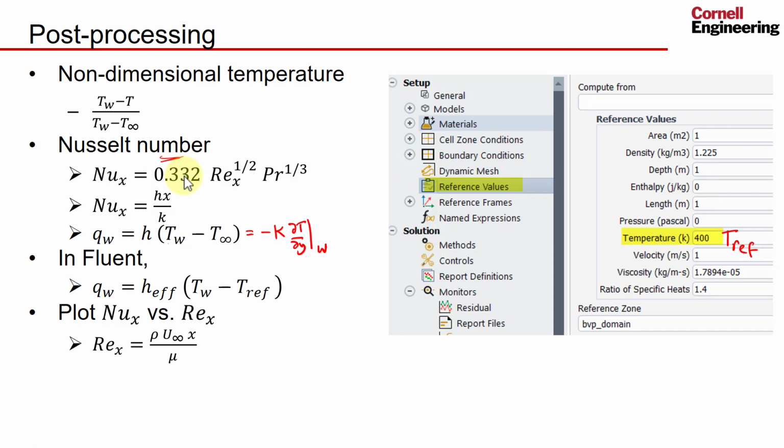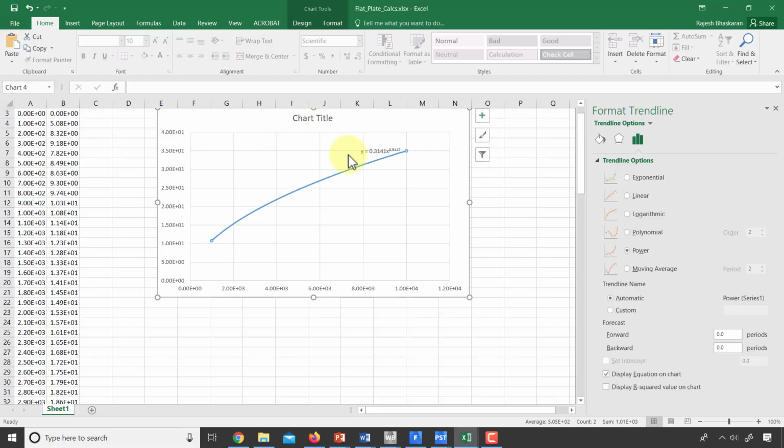There is some finite Reynolds number effect, and there are some mesh effects. You can also increase the number of samples along your line. All these things will make it agree better, but that can be quite painstaking. But that's a good way to at least get into the right ballpark for the power law fit. And you can save your project.